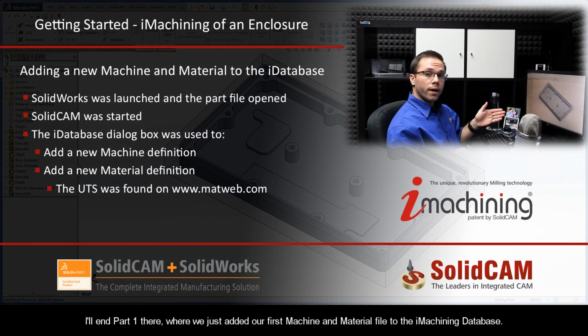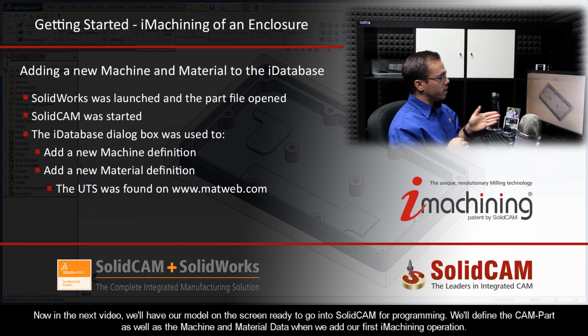I'll end part 1 there, where we just added our first machine and material file to the iMachining database. Now in the next video, we'll have our model on the screen ready to go into SolidCAM for programming. We'll define the CAM part, as well as the machine and material data when we add our first iMachining operation.